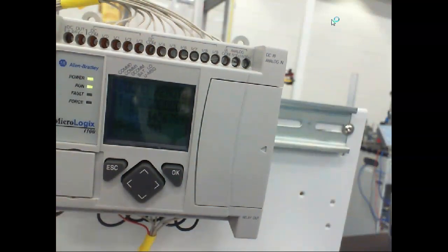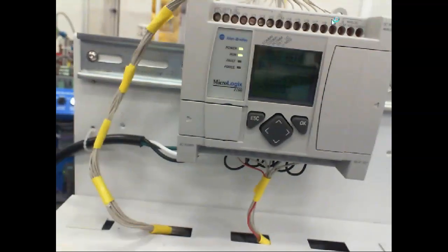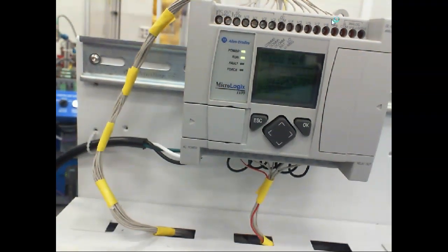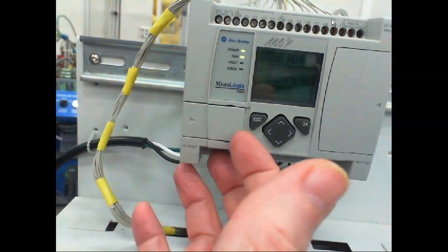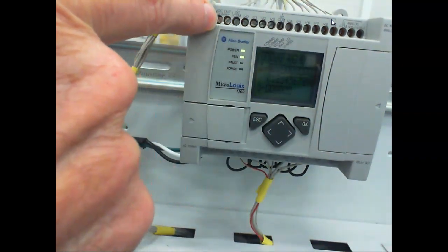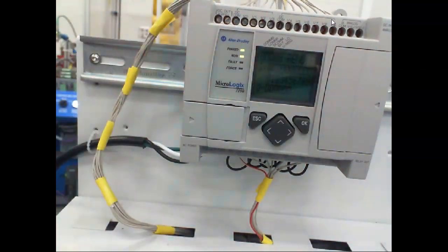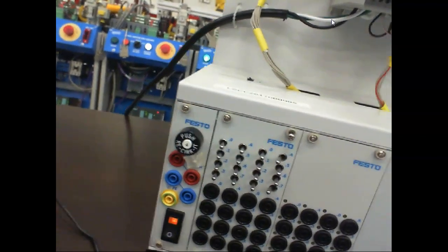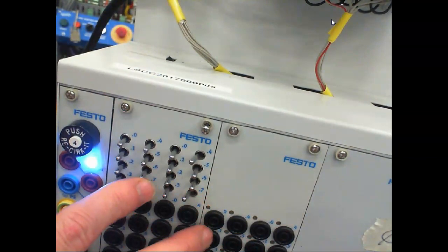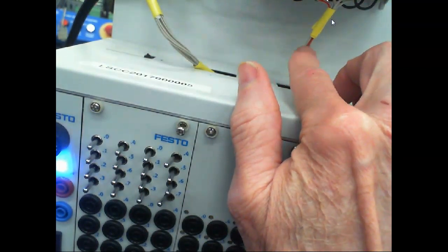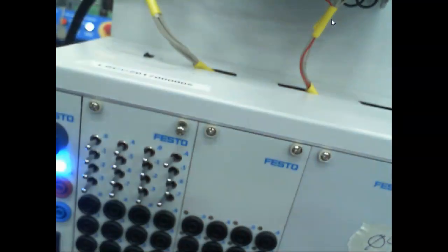So this PLC powers up off of AC. Well, some PLCs do. This guy's got an internal power supply on it. It's just that this power supply is not designed to run a lot of current. It could run switches and push buttons, but it couldn't run an inductive sensor or any of the solid state or electronic sensors that we'll look at. So what we're doing is using the power supply inside this guy. It has a nice DC power supply in it, and then they run the power up through here. So the red wire is plus 24 volts, and for this one over here you'd have to just look at the wiring diagram.